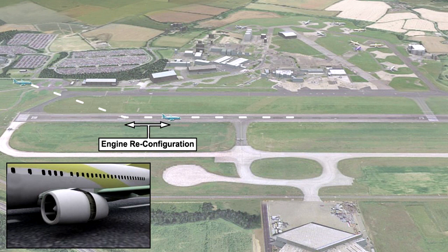It is important to note too that jet engine reverse thrust cannot be maintained right up to the point when the aeroplane comes to a full stop. Reverse thrust must be deactivated before the forward speed reduces to a minimum value. As the aeroplane slows down, the redirected airflow may start to be re-ingested into the compressor, as shown on screen. This means that the jet engine recycles its own gas flow, which significantly increases the engine temperatures. But it also means that debris on the runway can be sucked into the engine, potentially causing major damage.